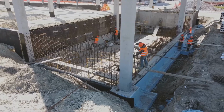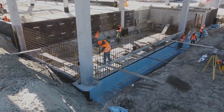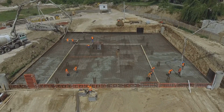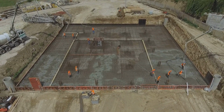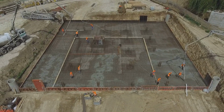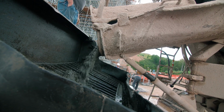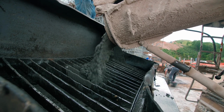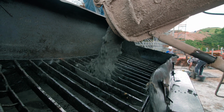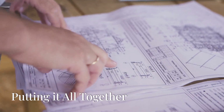Finally, don't forget about the subgrade and base material. This is the unseen hero that supports your concrete. This is the foundation underneath your concrete. A well-prepared subgrade ensures that the concrete will remain stable and level over time. The blueprint might specify what type of material to use, like compacted gravel, and how thick it needs to be to ensure proper drainage and support for your sidewalk. Proper drainage prevents water accumulation, which can weaken the concrete over time.